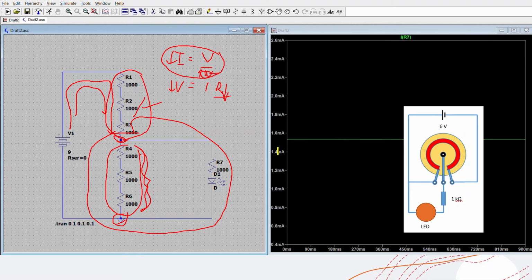The resistance across terminal 2 and 3 has decreased, meaning the output voltage across these 2 points has also decreased. Because of this decrease in resistance, there is a decrease in voltage, and the decrease in voltage led to the decrease in current in our external circuit. That is why the LED here has become dimmer.